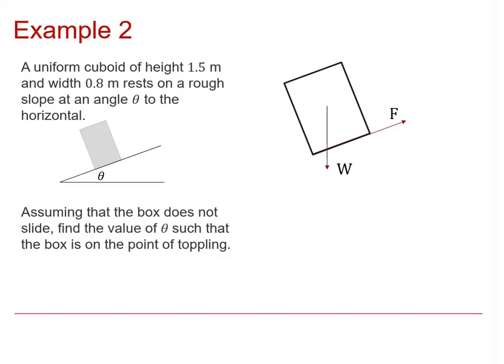But just as we can replace the forces on a rod, which arise from weight on each of its particles, by a single force through the centre of mass, in the same way we can consider that the normal reaction acts at one point. And we saw that in the previous problem where it acted at the corner, though that was easier to justify. But here we can put the normal reaction in one place, but we have to decide where.